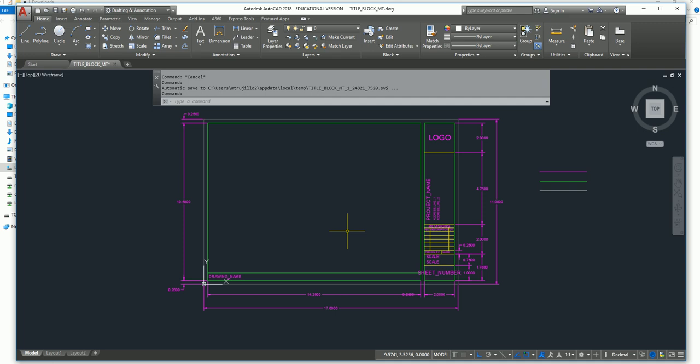And then sheet number, scale, you even have a little thing usually in there for who it's drawn by. That way, if your boss wants to know who drew it, they can go back for the revisions. Usually it's initials. And then, like I said, the revisions, the project name, address lines. Sometimes you have places for a consultant. So if you're an architect and the engineer's acting under your license on the project, you usually put their information under yours inside of your title block. And then usually there's a logo or a stamp or seal of some sort.